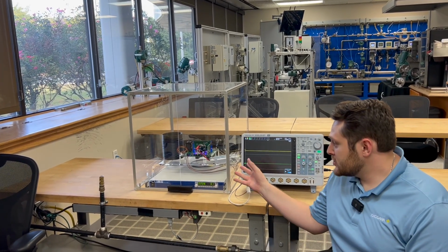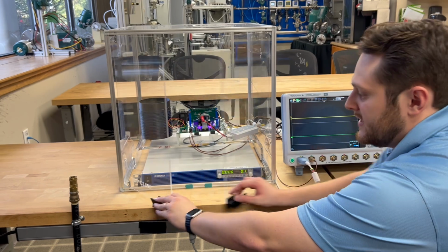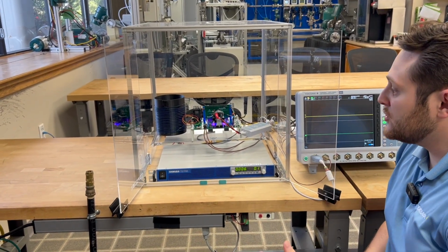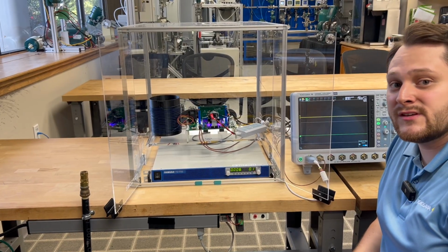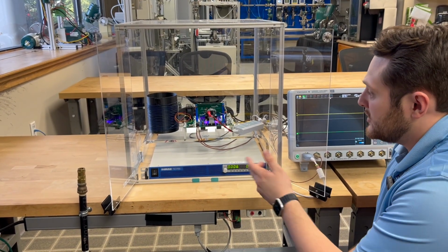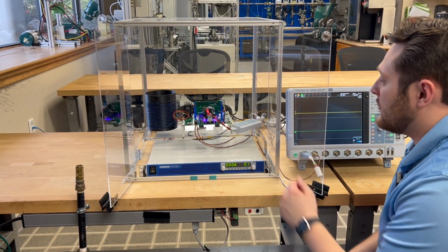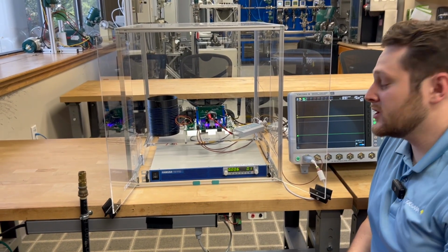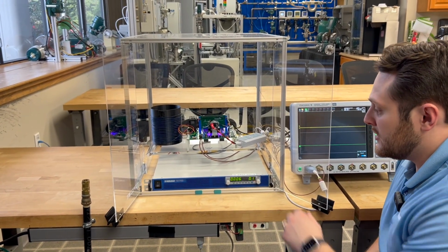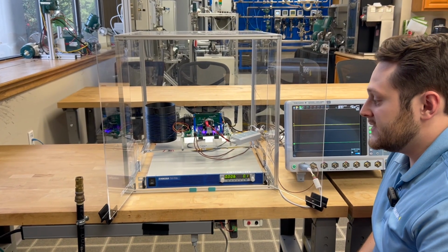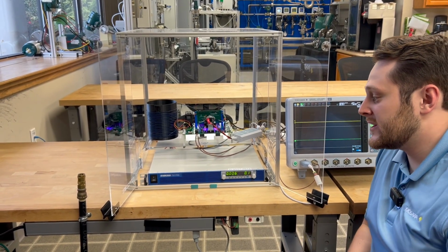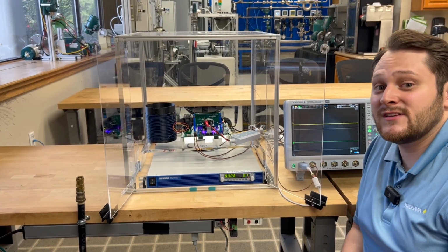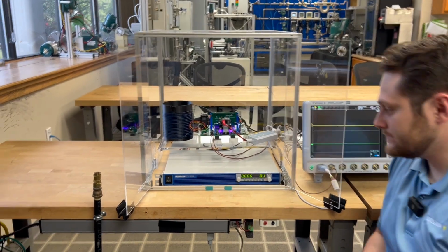For this test, I want to show you the test setup. In here, we have our test platform. It's an evaluation kit for a 650 volt SiC MOSFET. To do the differential voltage measurement, we have our PVDH 0400 1000 volt 400 megahertz differential probe. And then another thing to note here is our DC power source. This is a Kikusui PWX1500H. It is a 650 volt DC 1500 watt power supply.